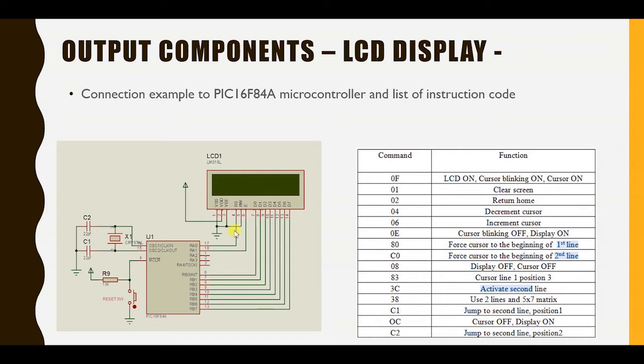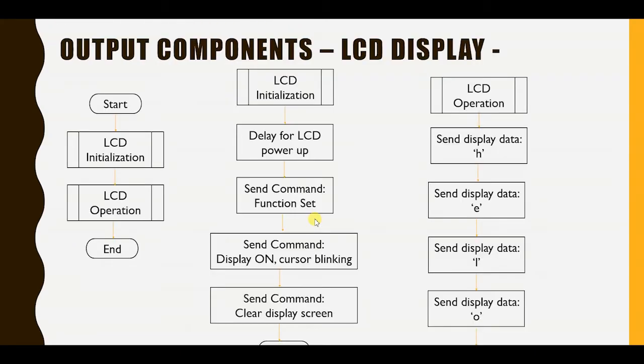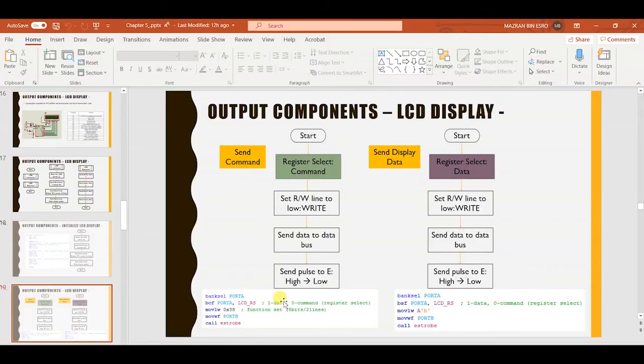So depends on you whether you want to put a command or data. The command or data depends on the status of the bit that goes into RS. If it's 0, it goes for command. If it's 1, it goes for data.